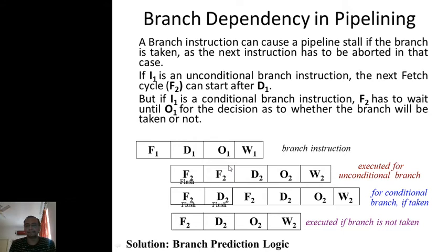If the carry flag is reset, the jump will not be taken. So a branch may be taken, or it may not be taken. In the case of a simple jump instruction, or unconditional jump instruction, or branch instruction, the branch is always taken.